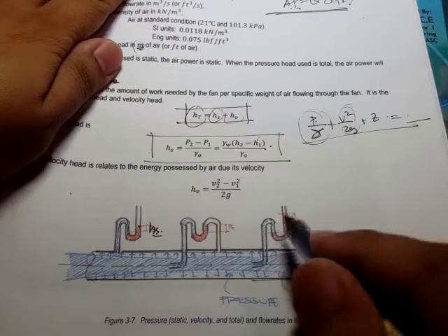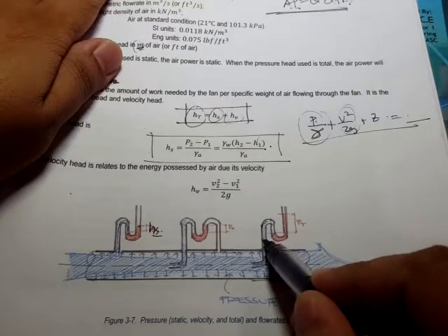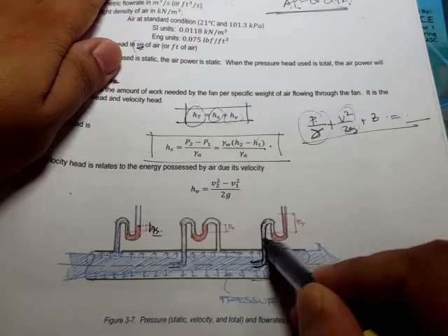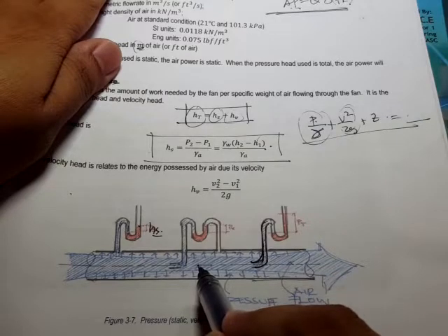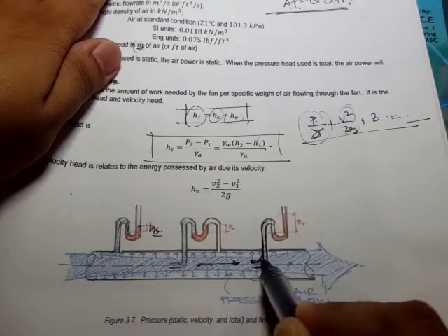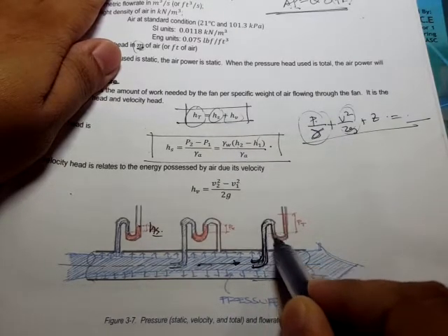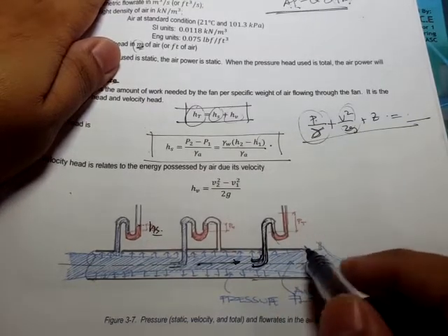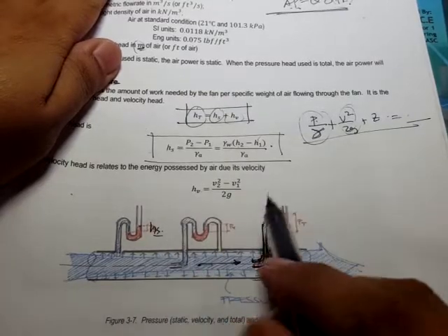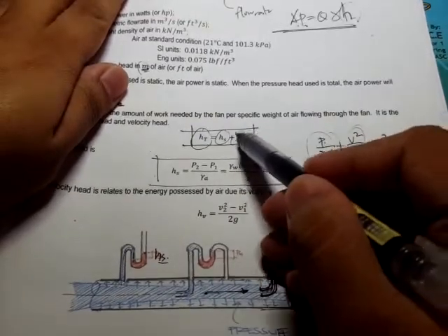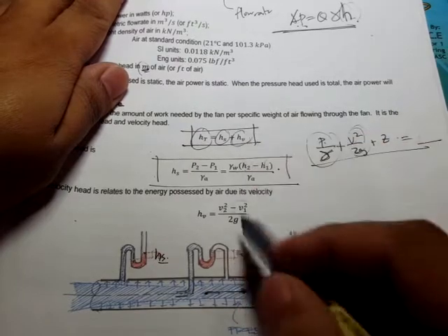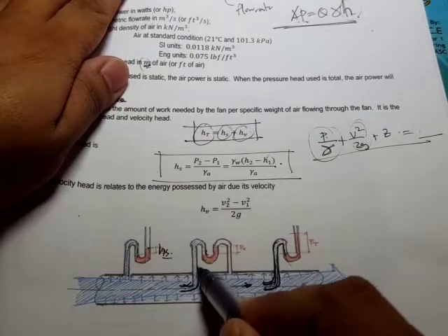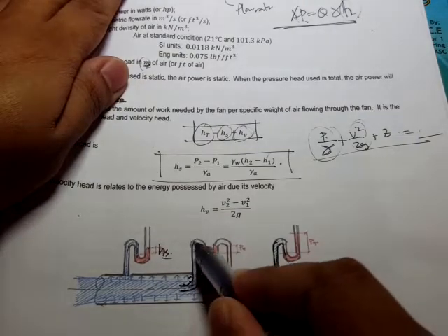And if we install the manometer this way, in the direction of the flow, then what we can measure there is the total pressure. So that's the total pressure. And another pressure is this velocity pressure. If we install this manometer in this way, we have something like the total pressure, and we have here the static pressure,